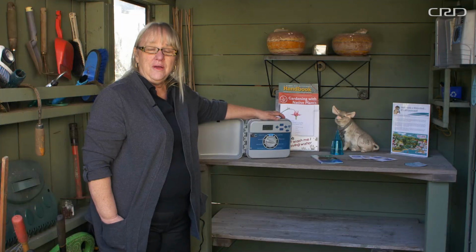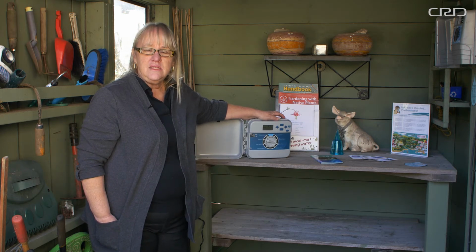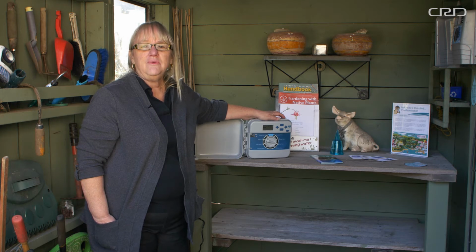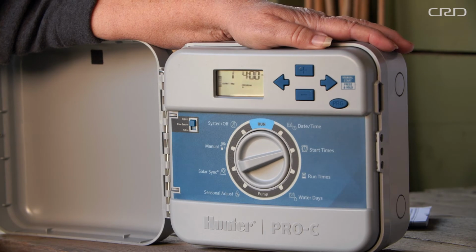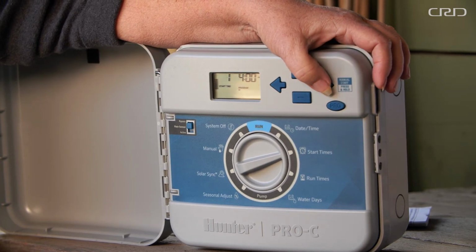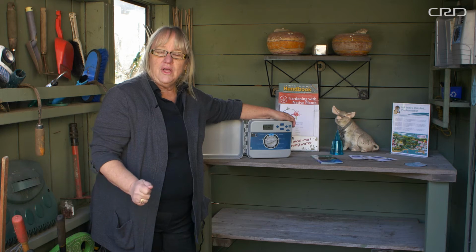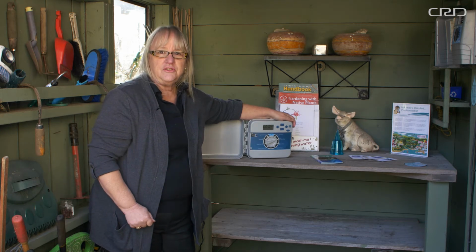So on our program, we had determined that we needed 10 minutes of operating time. To cycle and soak, what we're going to do is put in a second start time and reduce the run time of our sprinklers. So we turn our dial to start times. We already have a 4 o'clock start time under 1. Using our arrow, we go to our second start time. We want this one to start about an hour later to allow soak time and my irrigation to finish.